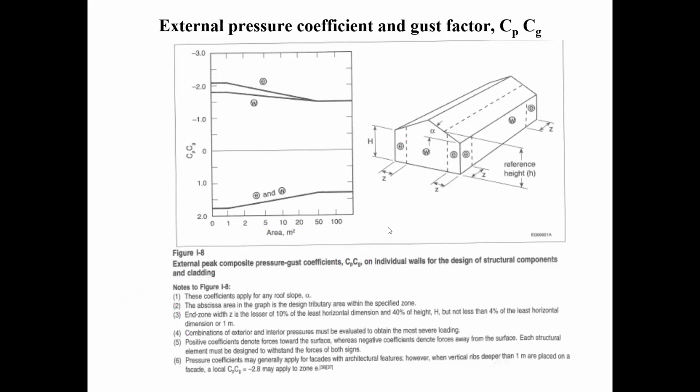Okay, so basically what I did here is I simply went here and I said, okay, here's my 1.4. What was the area? 1.44 square meters. It was about here. You don't have to be precise on this, guys. Remember, this is the area where the stud happens to fall, the tributary area of one stud.